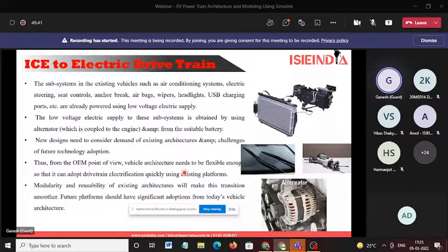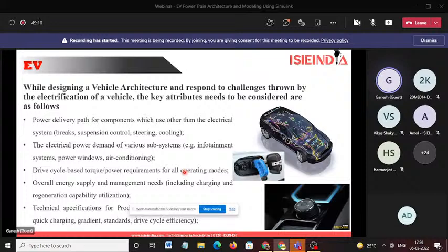The only thing is how you are going to transmit your power source from the rear to the front, how you are going to change your floorboard, how you are going to mount your batteries, how you are going to keep all your floorboard panels, and how you are going to connect your wiring harness. These are all the things you need to check. This is one of the most important things while designing, as vehicle architecture is responsible for the whole.